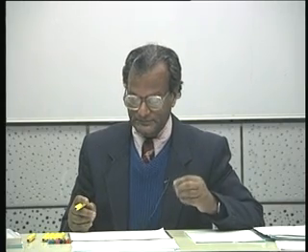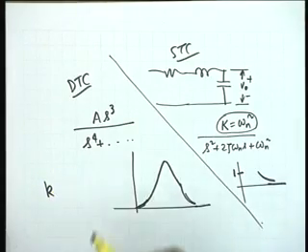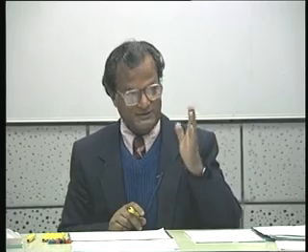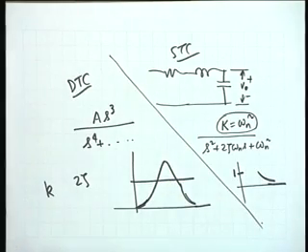It cannot be otherwise. And therefore in the double tuned circuit, irrespective of the values of k and zeta, and the relations between them, whether k is greater than, equal to or less than 2 zeta, whether the peaking circle intersects the j omega axis at 2 points or not, whether it touches at one point or it does not touch or intersect at all, it does not matter, there shall always be a maximum. If there is a maximum, there must also occur 2 half power points.